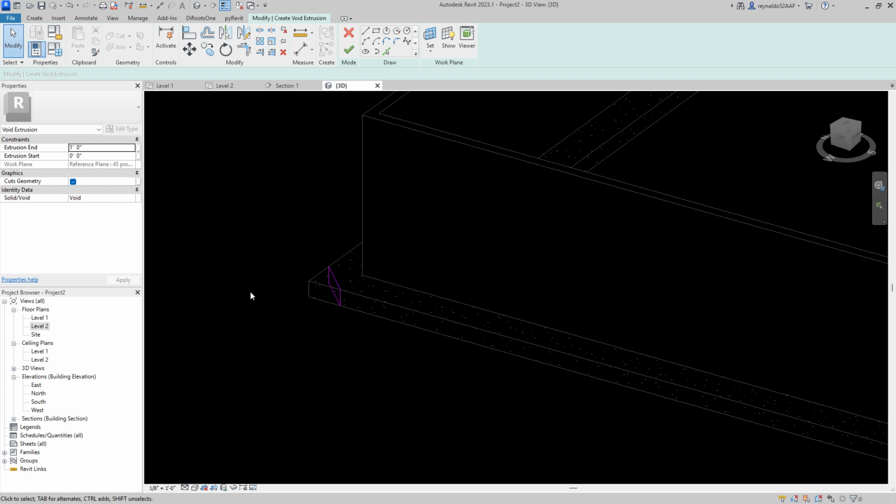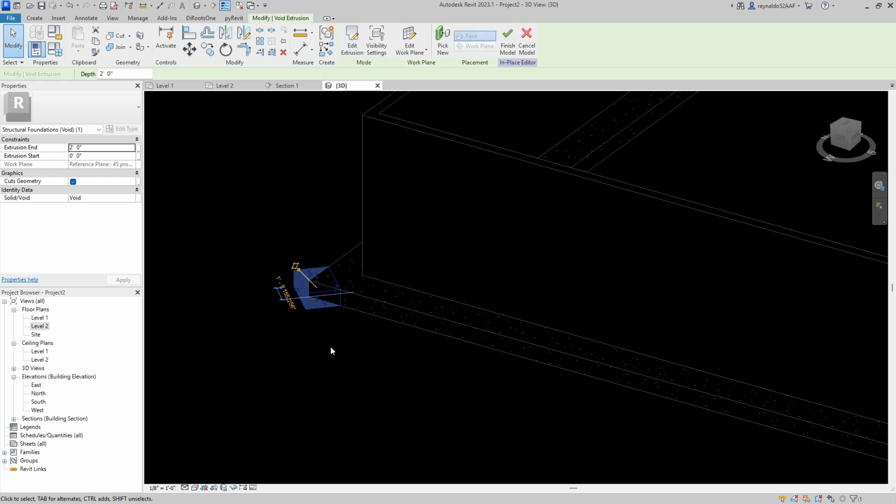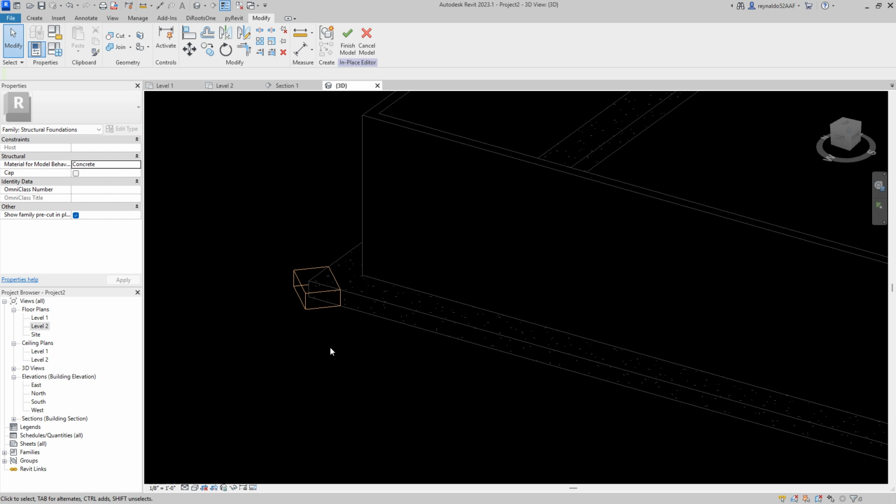The next thing you want to do here is put some number here so that the extrusion will go beyond this area. That's the only way it'll cut this whole portion off. It's got to go beyond these two side parameters. So I'll make it 2 feet and click OK, and then click OK. Click the arrow here, and there you go. It goes beyond.